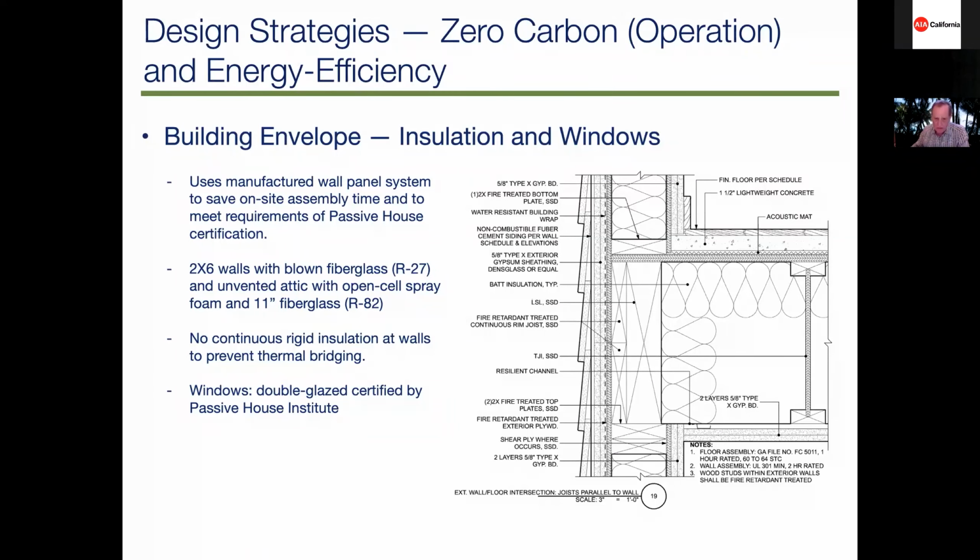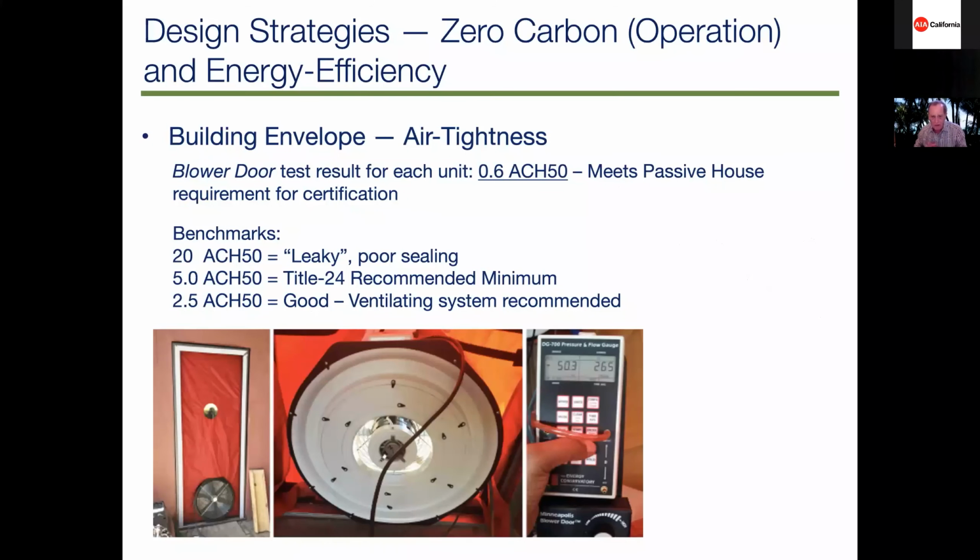So he bought their windows and, as I say, insulated the envelope to their requirements. Now here we go with the air tightness. The Passive House does require an extraordinary airtight construction. And they did a blower door test on each unit, each level.